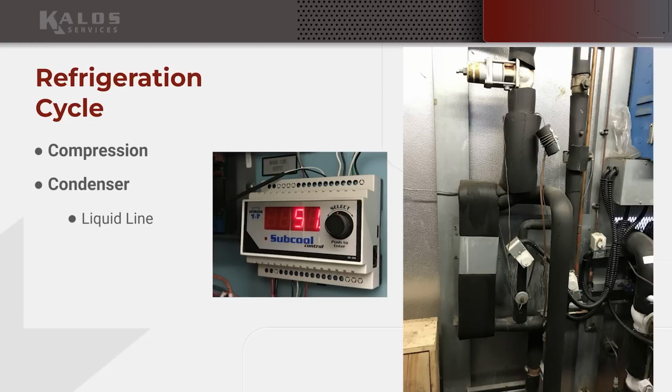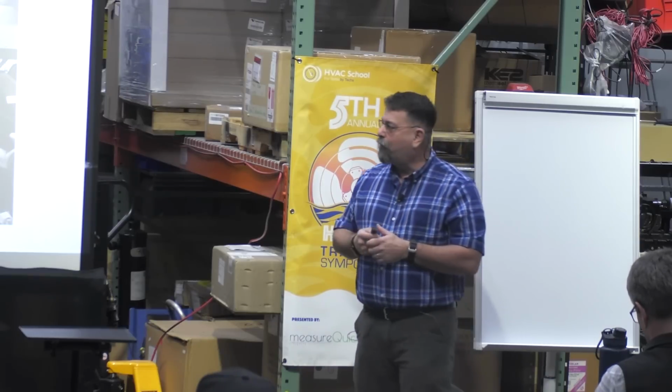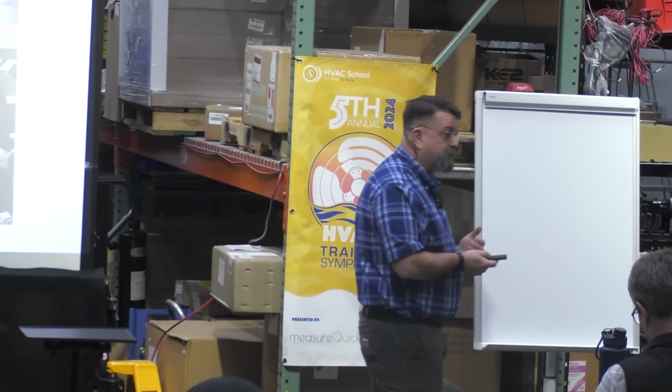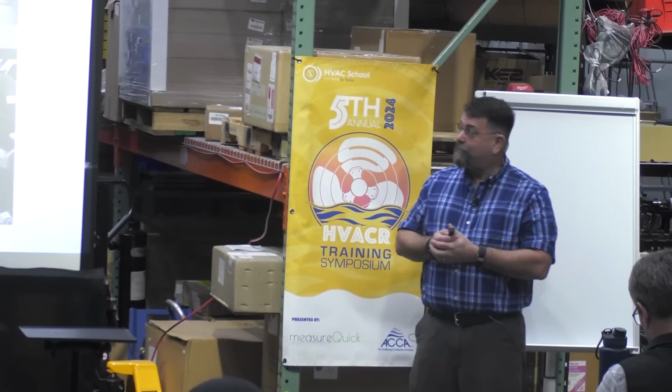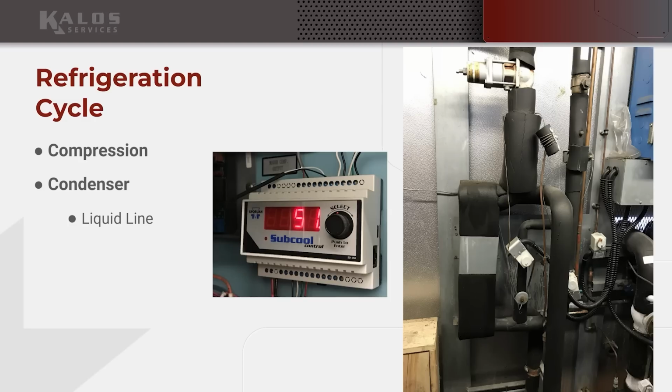It's just a plate heat exchanger, okay? Some of you guys up north right now online are going, yeah, we do this all the time. Some guys down south, Florida, might be going, I really haven't seen too many heat exchangers. So what do we got going on here? Just a plate heat exchanger. One side, one half of this thing is an evaporator. It's going to be piped to my rack. I'm going to feed liquid to a TXV, right? It's going to boil inside. It's going to absorb heat.